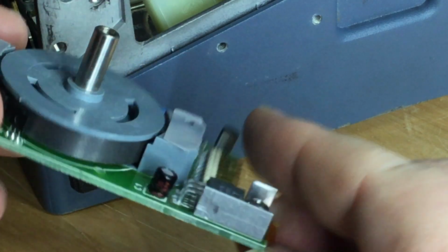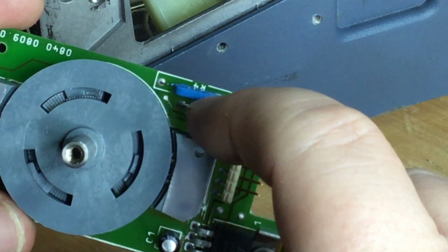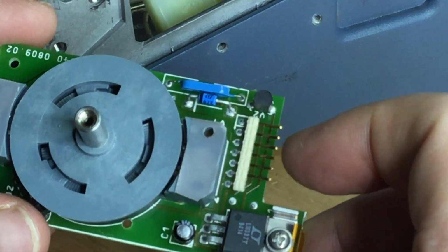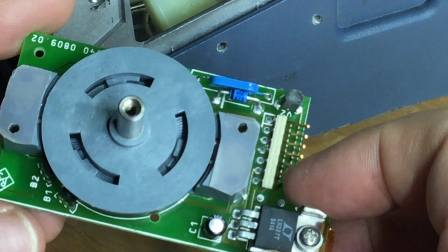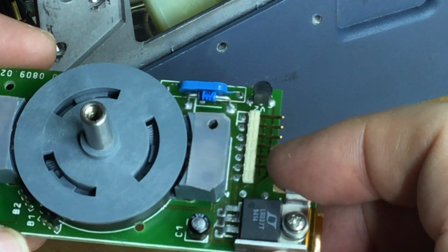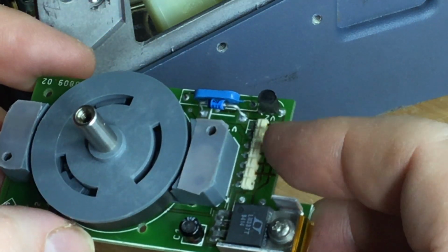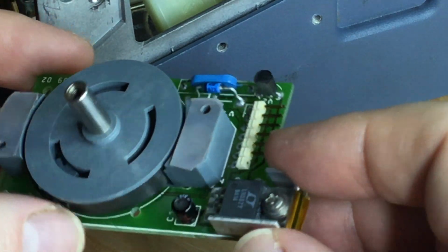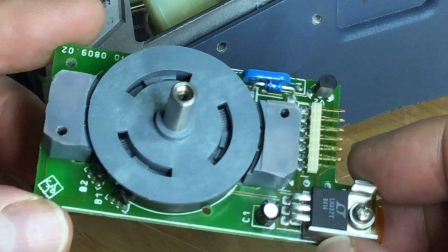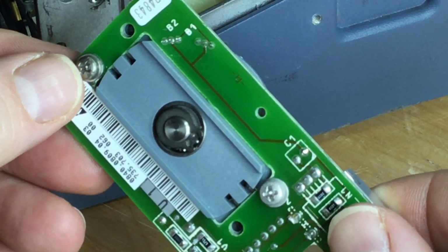But we've got a voltage regulator, an LM series voltage regulator, then a diode and a high precision resistor, transistor here as well for controlling other aspects of the brightness and contrast control, I think. So it'll just be a case of finding the right pins on this connector and then doing some tests, I think, with the oscilloscope before we go any further.